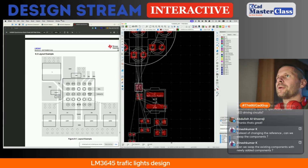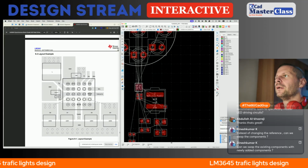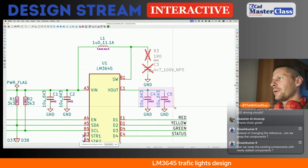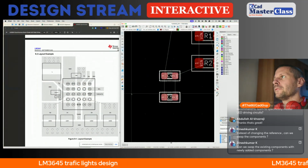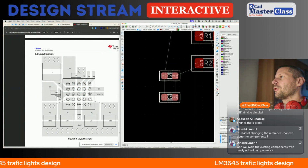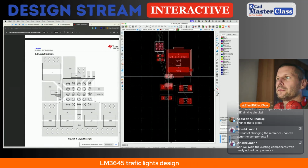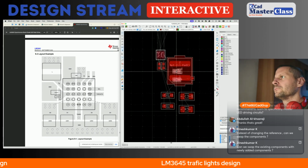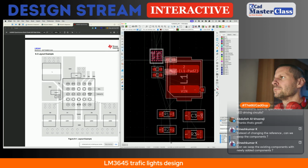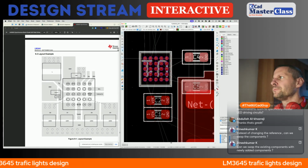What else is on the schematic? The output capacitors near the C1, okay. And the snubber components that must be close to the switch node. The output is near here.